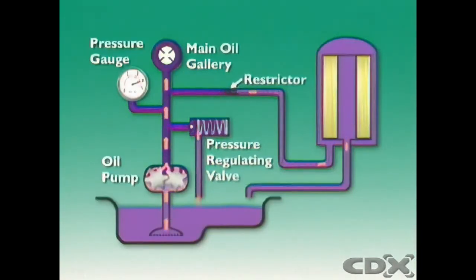In a bypass system, the bypass element filters only some of the oil from the pump by tapping an oil line into an oil passage. It collects finer particles than a full flow filter. After this oil is filtered, it goes back to the sump.